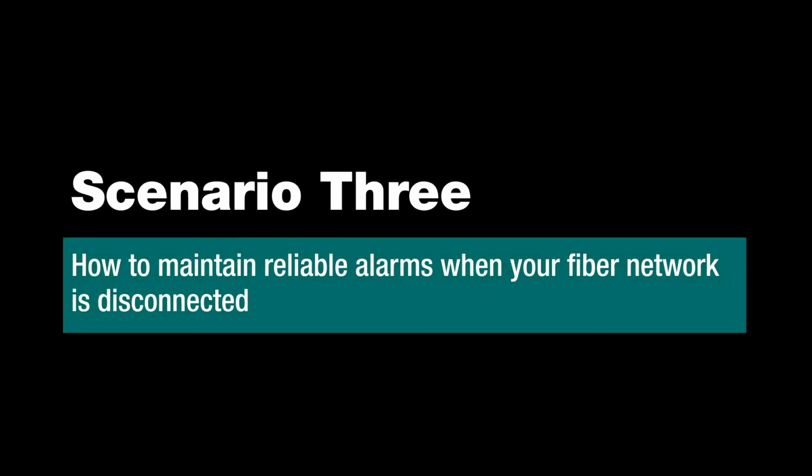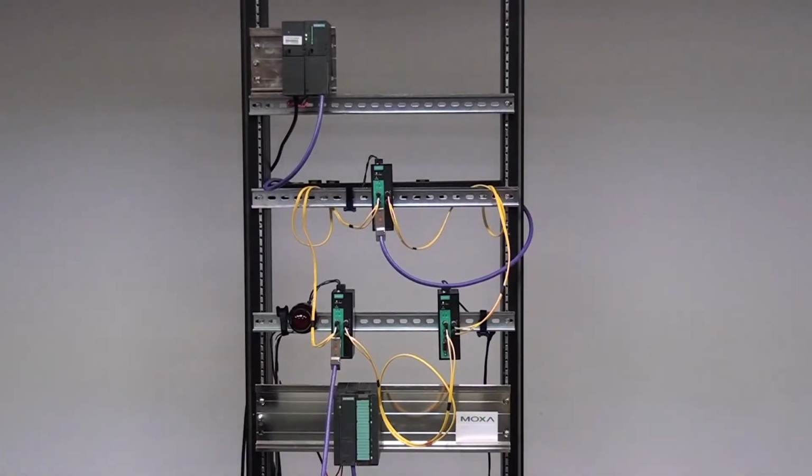Now we're in the operational phase, and the PLC is interacting with the Profibus slave devices through this redundant ring. The network redundancy is good because it allows the Profibus devices to continue to communicate down a backup cable if, for example, one of the fiber cables is accidentally cut.